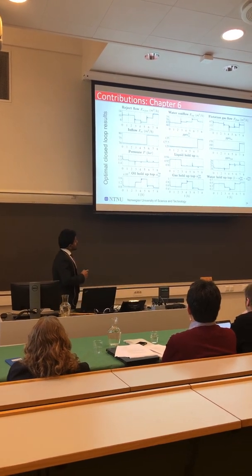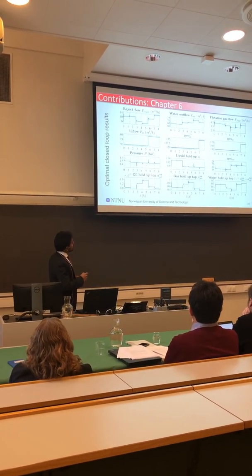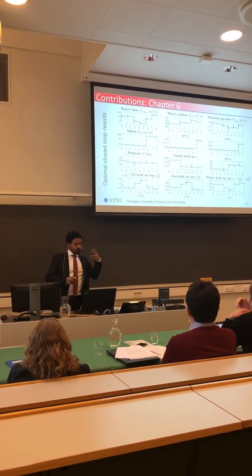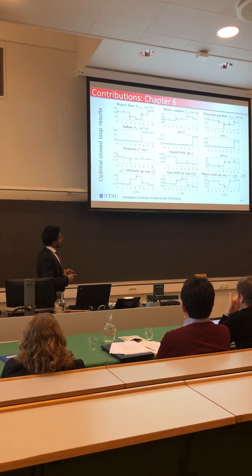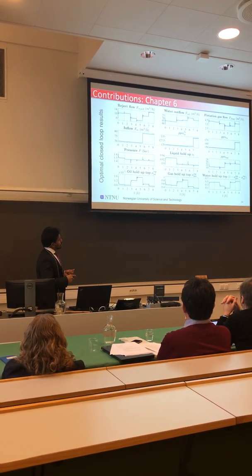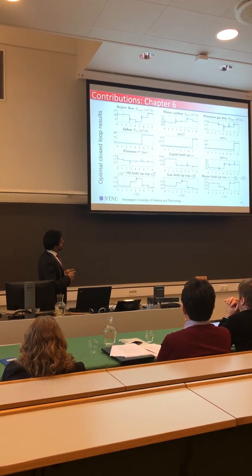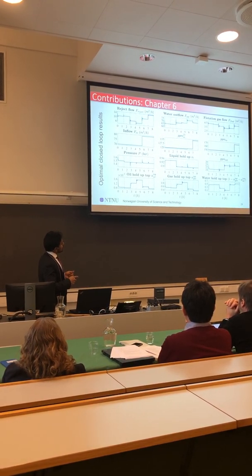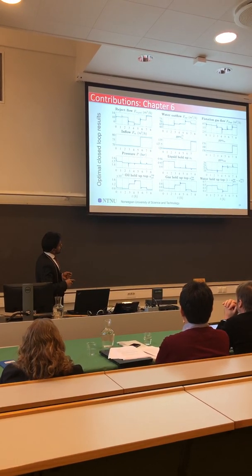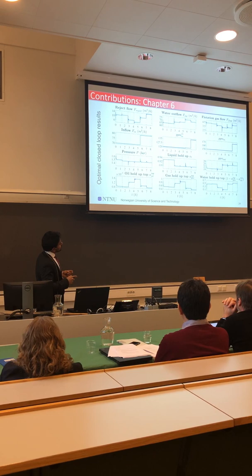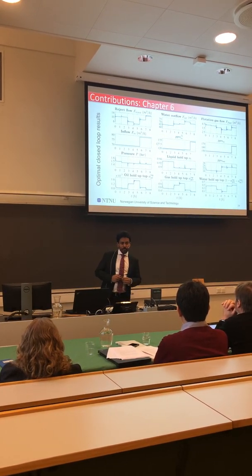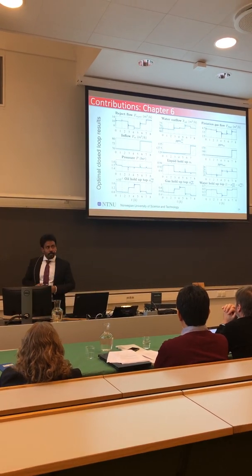There are some other variables that are plotted here: the oil holdup at the top, the volume fraction of oil going into the reject stream, the volume fraction of gas going into the reject stream, and the volume fraction of water going into the reject stream. As you can see, as we move closer and closer to the optimal, which is here, here, and here, at this point after 4 hours, we see that the flotation gas usage is the minimum. And that clearly proves that our optimization results also work on closed loop simulation.